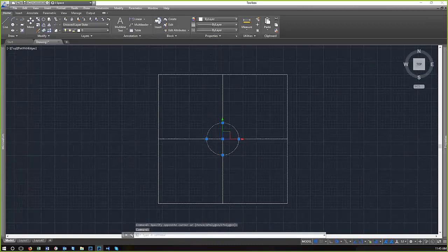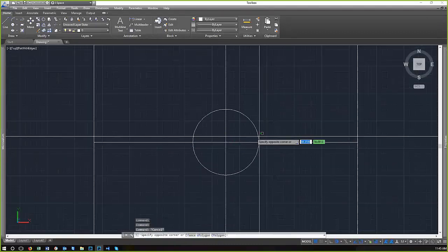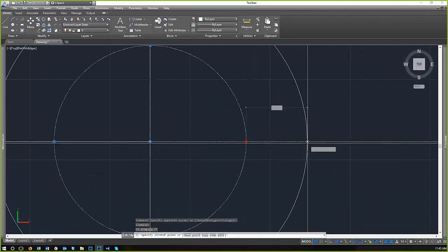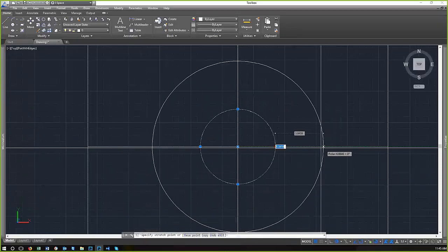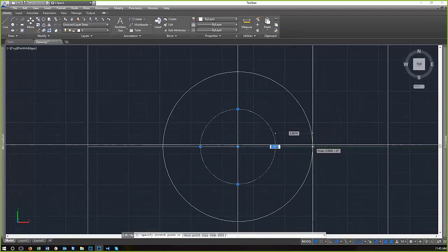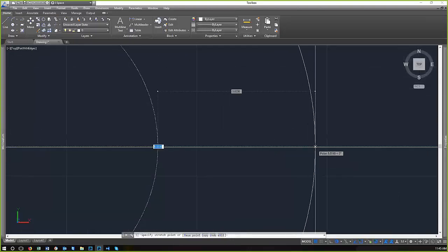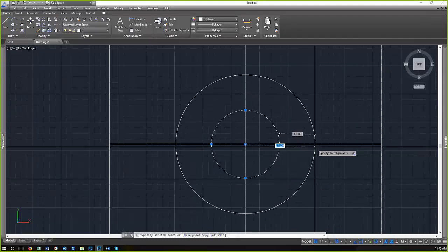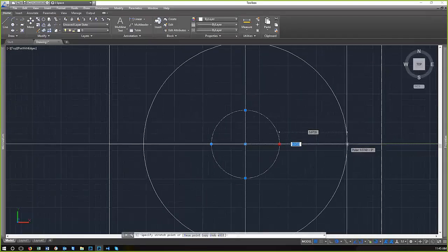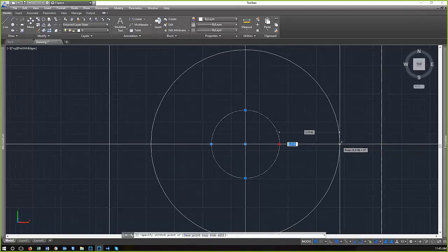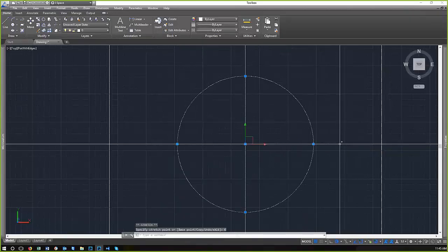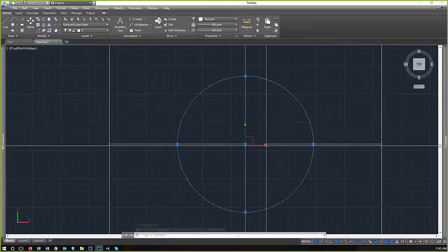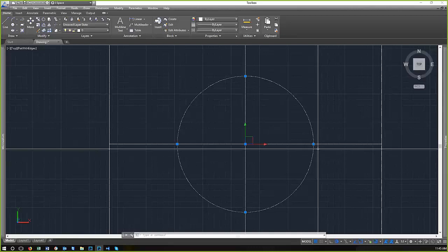If you click and drag this out and you try to click on, that was a 6-inch diameter, so let's go 6-inch radius this time. If I tried to click on 6, it would be really hard or impossible. But you'll see there's pop-ups, and when you're dragging, you can see that dynamic input box come up where I can type in just 6 and it'll make it 6. So using the keyboard, using your properties and typing, it's going to keep your drawings accurate.